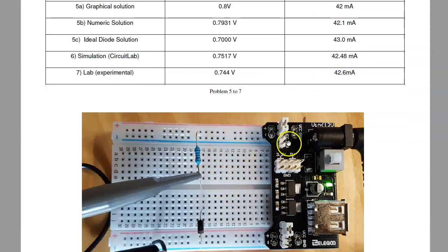And I can also build it in lab. So these breadboards that you have, the outer rail is 5 volts. So the red one's 5, the red or blue is ground. That's the plus minus. I'll take a resistor from the 5 volts, here's my 1K resistor, to a diode to ground. That line means the direction of current flow. That's the arrow for the diode.